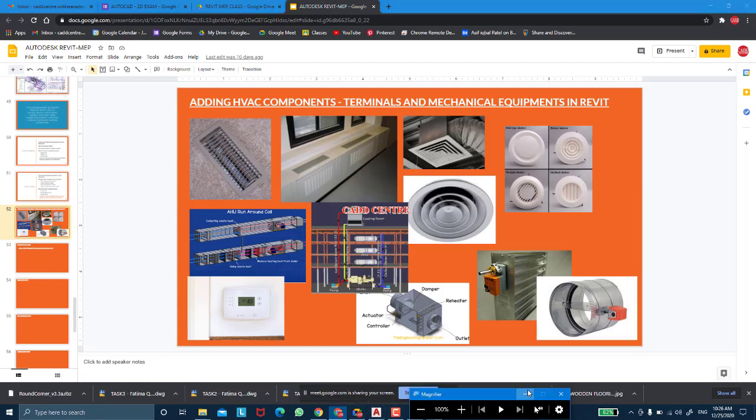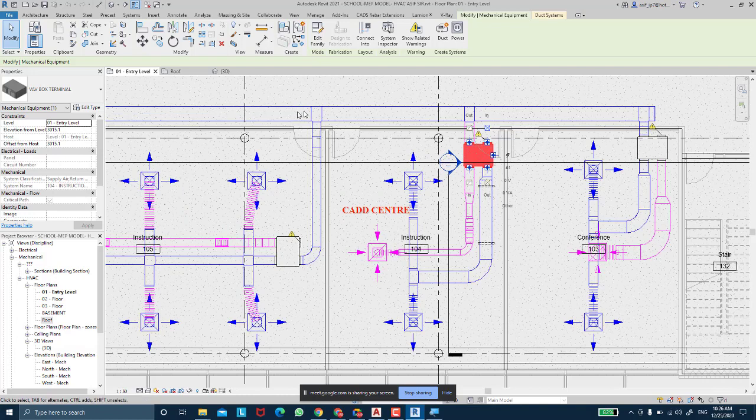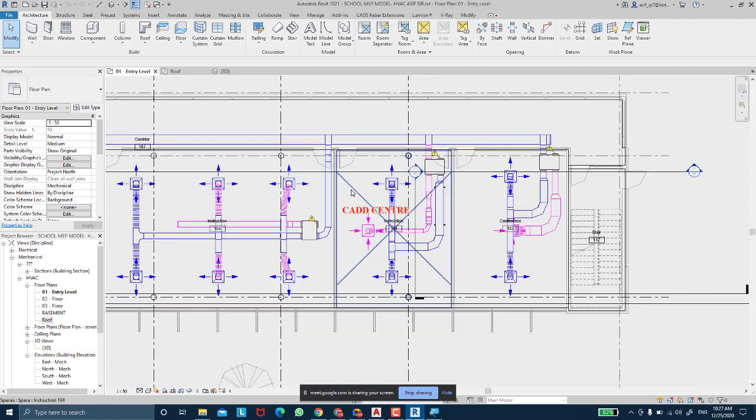That means in this particular room you will not receive any fresh air, because I'm telling my VAV to shut the fresh air from coming into this duct and being supplied over here. But in the main duct there is a continuous flow. You can see this is my main duct. The air will constantly flow, but if this is turned off, this room will not receive any fresh air. If I turn it on, it will pass through and supply fresh air again. That's how the system works.